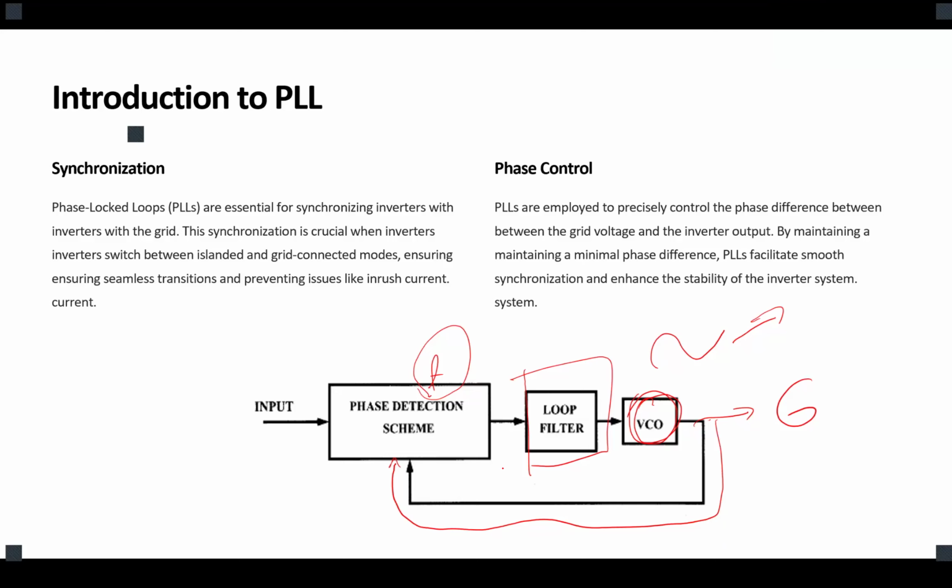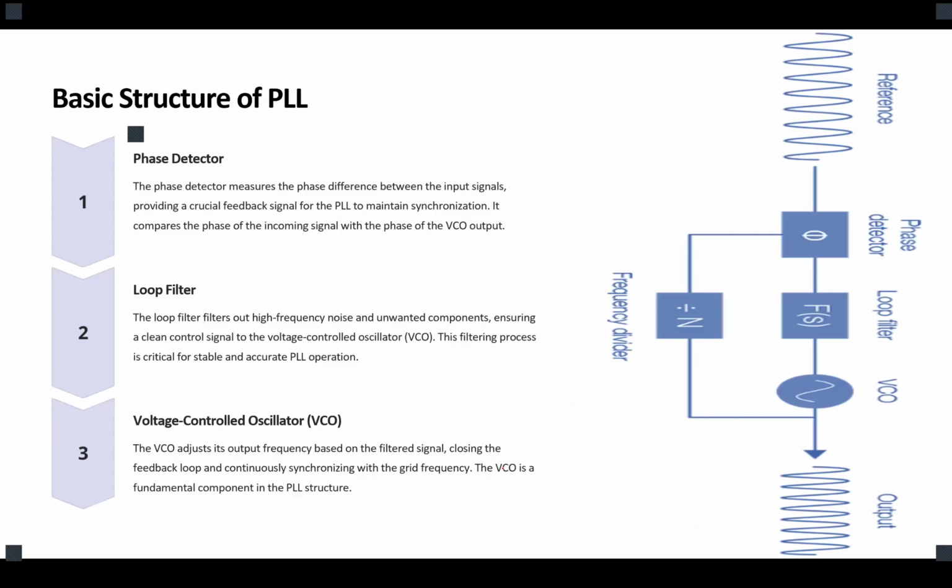So the filter works to eliminate all those noises and unnecessary high frequency variation. That way your detector signal is smooth, so those noises would not affect your oscillator when it wants to create a sinusoidal voltage based on that real-time detected frequency.